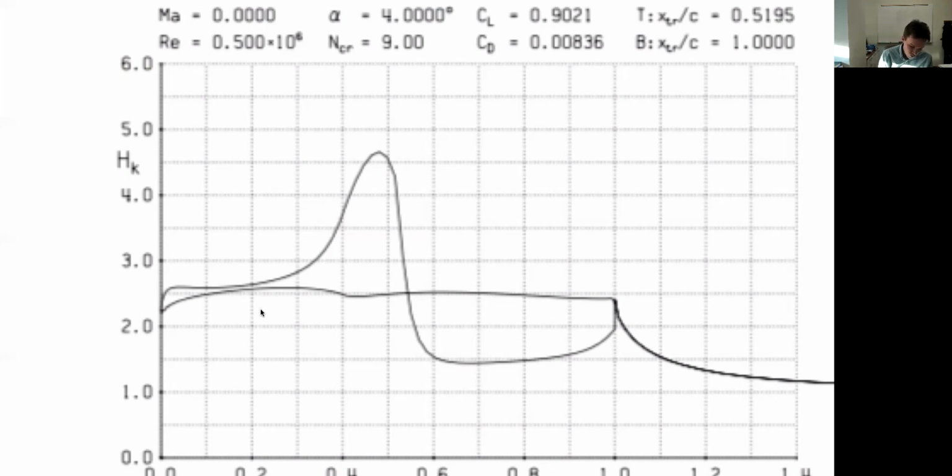And in fact, a typical rule of thumb is that for a flat plate, it's a simple geometry, but for a more typical geometry, H greater than 2.2 is an indication of, say, transition or separation. Somewhere around there. That's just a rule of thumb, right? As it gets larger. So in this case, we can see what's happening. It's starting out relatively flat, and then it grows, and now it's getting big. So we're going to transition to turbulent flow, and now that we're bringing in that momentum, that extra energy, H goes way down again, and then it's starting to grow again towards the trailing edge.